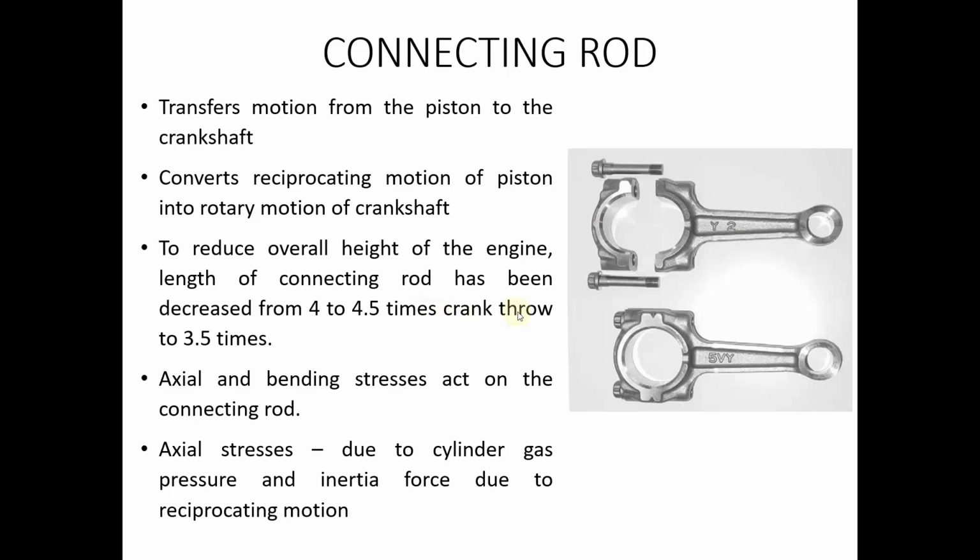Now, what is crank throw? That also will be seen. Crank throw usually means 1/2 of the crank revolution. Crank throw is usually the 1/2 of the stroke length. The stroke length, you know, is the piston travel from the top dead center to the bottom dead center. So 1/2 of that distance is known as the crank throw.